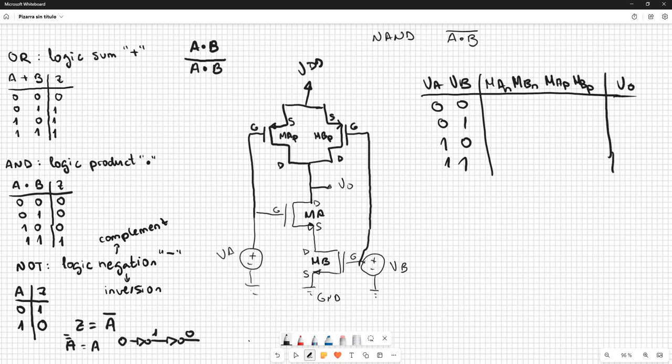So now, in the case of the CMOS, it's much simpler, because if the base is in cutoff, the load is in ohmic, and vice versa. So in the first combination, we have 0 at the gates of the NMOS A and B, so they are going to be in cutoff. If they are in cutoff, their complementaries are going to be in ohmic. Remember that from this table.